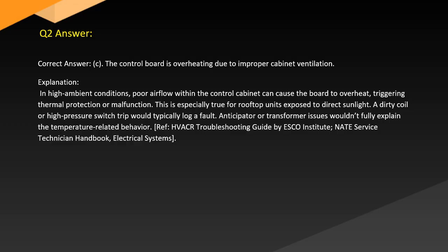A dirty coil or high-pressure switch trip would typically log a fault. Anticipator or transformer issues wouldn't fully explain temperature-related behavior. Ref: HVACR Troubleshooting Guide by ESCO Institute, Service Technician Handbook, Electrical Systems.